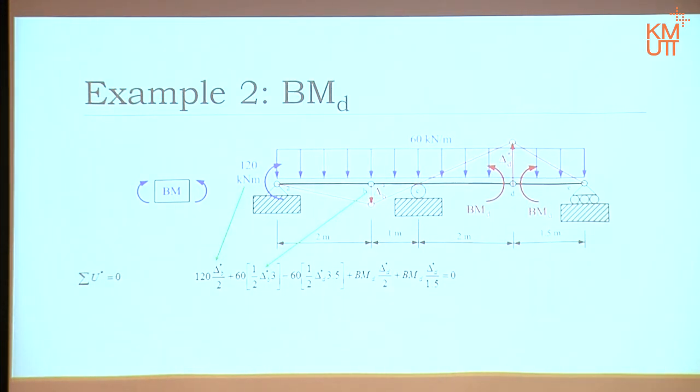Okay? So that's cope with that one. Now, notice that force coming down, displacement all come down. Therefore, this part is positive. Next, that part, the force comes down, displacement goes up. Triangle but going up. Therefore, this work is negative. The work is equal to the magnitude itself, 60, times that area, which is again a triangle, a half times the 90 degree height times the base.